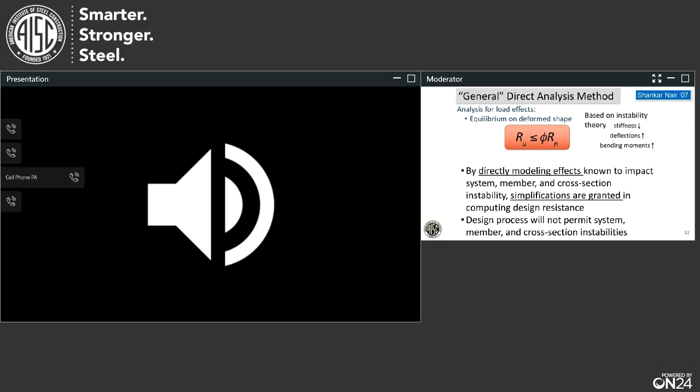If I have more of a normal truss that might be used as a lateral system in a building, in a 5-story building or something, then it's interesting, because in general, with all these pin connections, you'd be thinking of K factors equal to 1. The effective length factor would tell me K equals 1, and the direct analysis method is telling me K equals 1, so I just use K equals 1 and whichever method is the easiest.